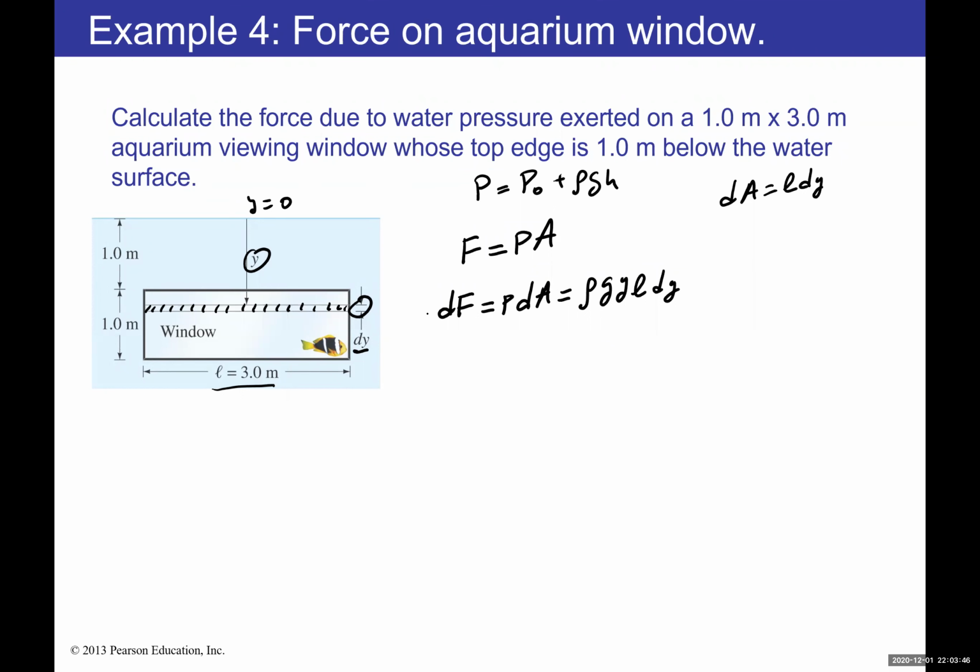Then I'm going to integrate both sides. On the left side, the integral of dF is just the force. On the right side, I have the integral of rho g y times L dy. The limits go from the closest point to the surface, which is 1 meter, to the farthest distance from the surface, which is 2 meters.